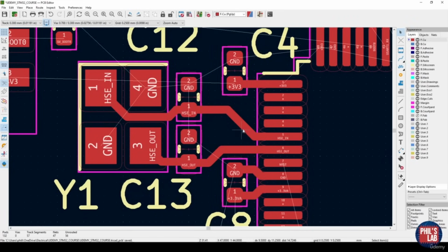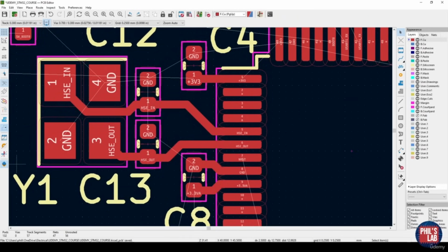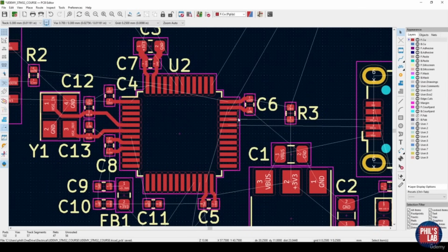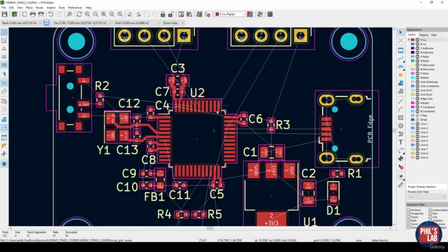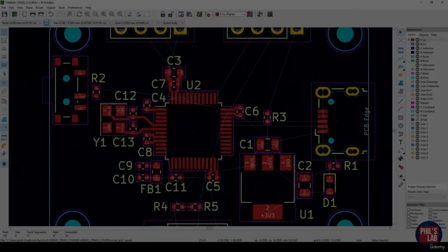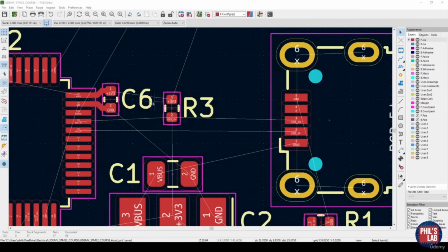So this is really simple. The main thing you have to maintain is proper spacing, and when you can, try to break away from sensitive signals and traces. So my recommendation is to do sensitive circuitry first, and that includes decoupling capacitors, and then we can move on to doing USB and the various other peripherals before we then do the power sections. So now let's move over to the USB differential pair.